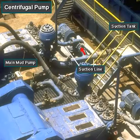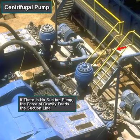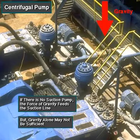The small pump takes the mud from a suction tank, moves it through a line connected to the main pump's suction line, and keeps the suction line full of mud at all times. If the system does not use a charging pump, the force of gravity alone feeds the pump's suction line. Sometimes, gravity cannot keep the pump's intake completely full of mud. The pump pistons suck in the mud so fast that gravity cannot keep the suction line full of mud.